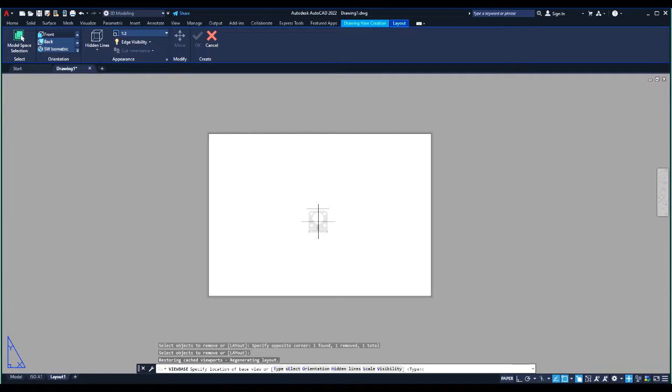The next thing you also want to do is to come over to your drawing view creation. You notice we have our scale. The scale is being reduced at the moment, so we can just click here and bring it back to 100% of the scale. You also have other options of bringing this: either you want to bring it as visible lines, hidden lines, and shaded. I will go with the default. So I'll just click anywhere here. Once I click anywhere there, that's pretty much all I need to do.